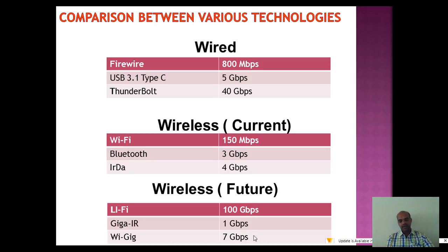This is using the latest modulation techniques called BPSK, QPSK, and 16 QAM, and this also works in the 60 GHz unlicensed frequency. There is no need of any license to use this particular technology.